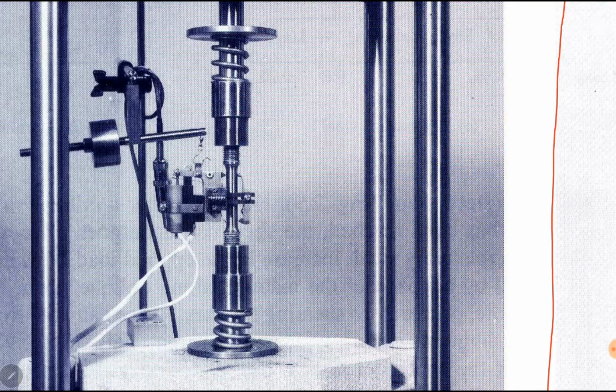Okay, in the necking region, we can see that the area is decreasing continuously. This decrease in area is actually another type of strain. It is decreasing in the lateral, transverse direction. Although the load has been applied as an axial load, the area is decreasing in the transverse direction.